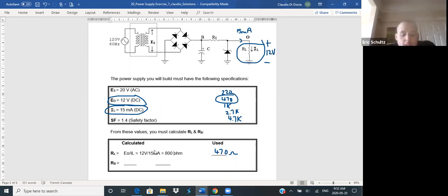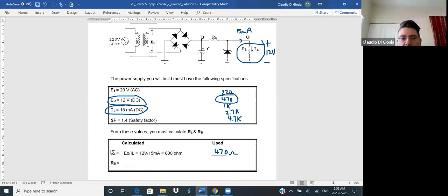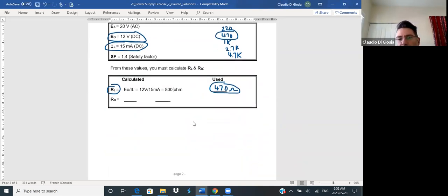Okay, so I don't know if you noticed, but did we use this RL value anywhere in our calculations? We haven't. In theory, when we assemble the circuit here, the assembled circuit will have that RL resistor here. So for our calculations, we don't actually need the RL. The RB is a different story. The RB is on the next page.